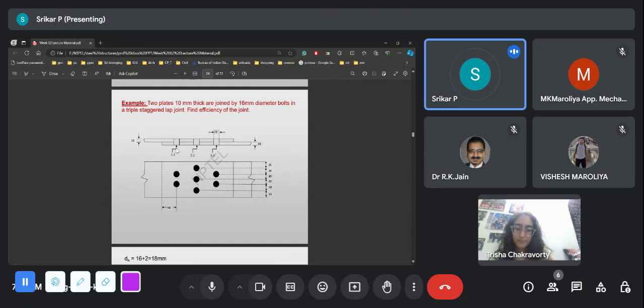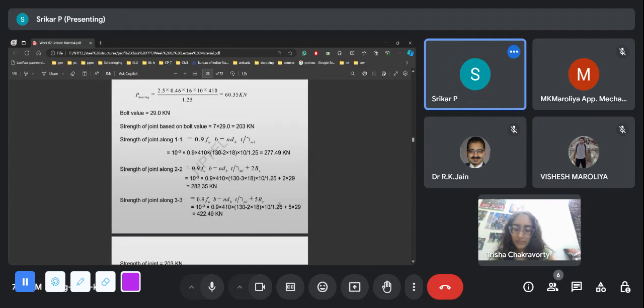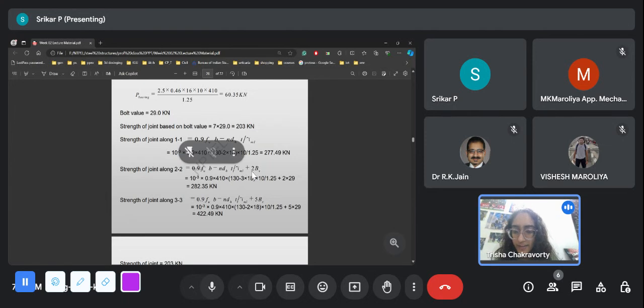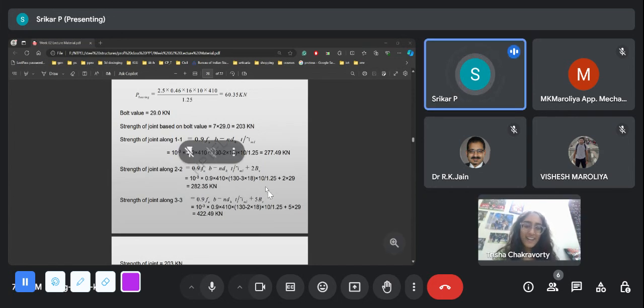So when we go to section 2-2, we add 2 times BV, because that has already been taken by the bolts. Section 2-2 can take an amount equal to its own strength plus 2 times the bolt value that has already been transferred. It can always take an additional force of the bolt value times the number of bolts in its previous section. Okay, a little convincing.